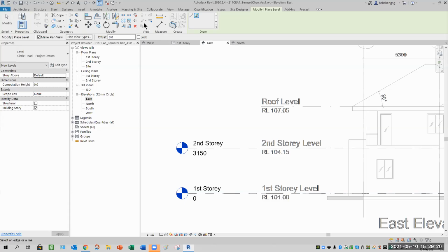You can only insert now once you have your plan created first with the grid, before you can import all your elevations. So you need to do your plan view import first before you do the elevation. You remember last week we did that.